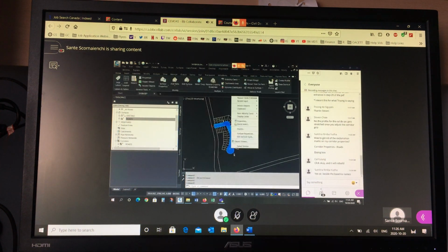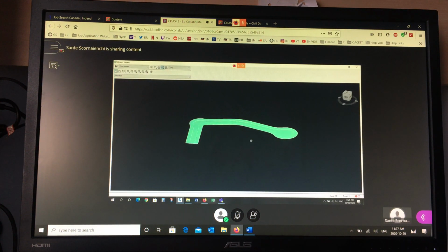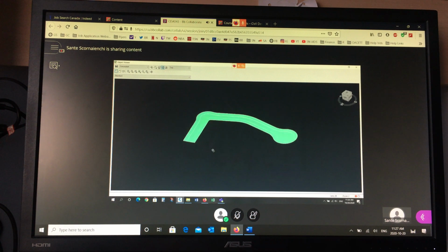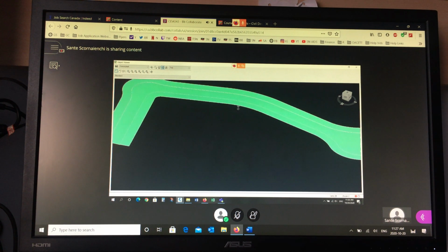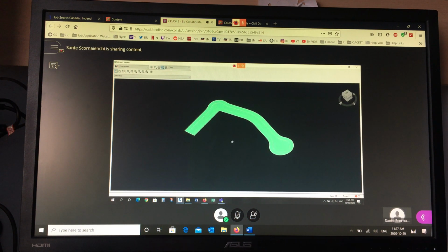And look at the surface in 3D, object viewer. And that's pretty good, not a bad surface. So that's what you're looking to do to create this finished ground surface. Okay? This surface is used for the front lot corner elevations, which I'll demonstrate again in a moment, and it's used for the top of maintenance hole elevation when you do your pipes down on the pavement. Okay? So that has to be good.